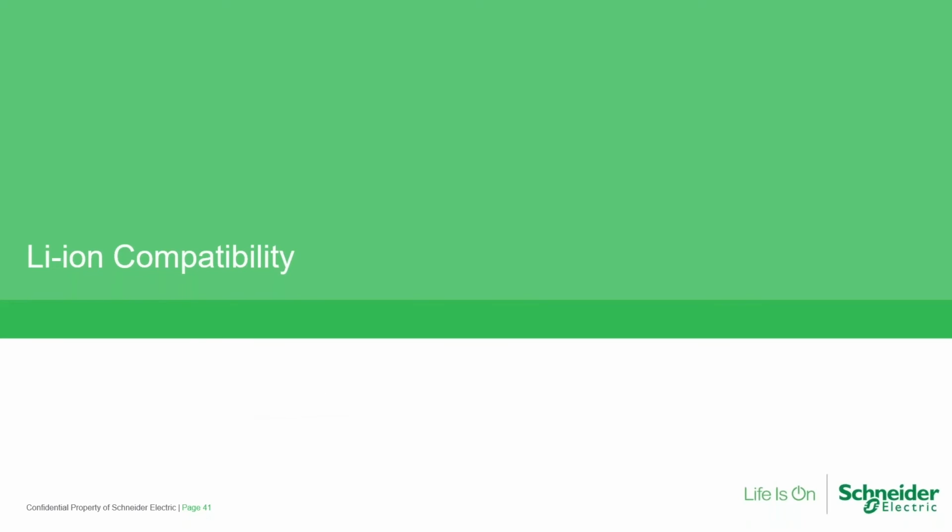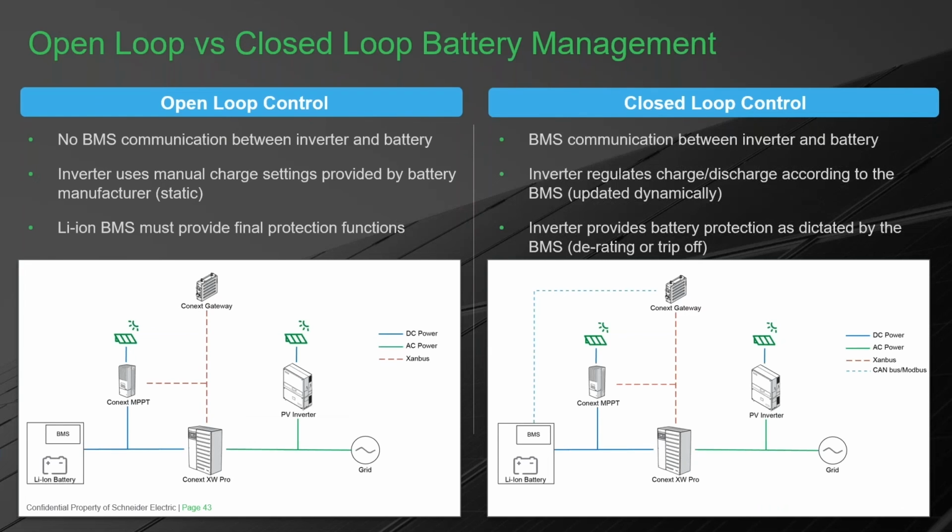Okay, I promised we were going to talk about lithium batteries. And I promise I'm going to give you names. I'm not just going to talk in general here. So let me cover lithium batteries a little bit here. Very important that the lithium battery that you select has a built-in BMS, because the lithium battery has to be able to monitor itself and protect itself.